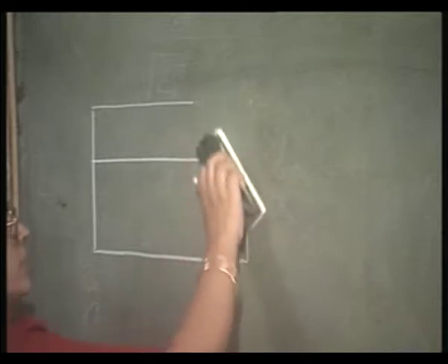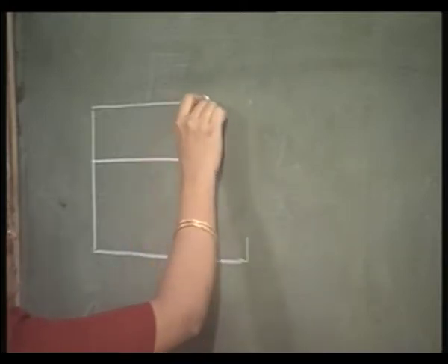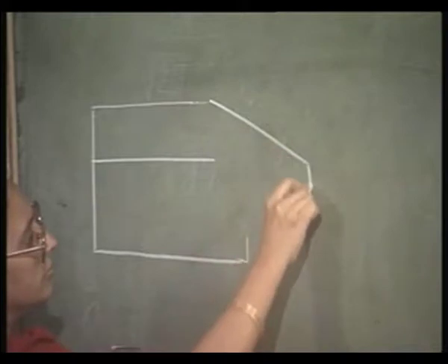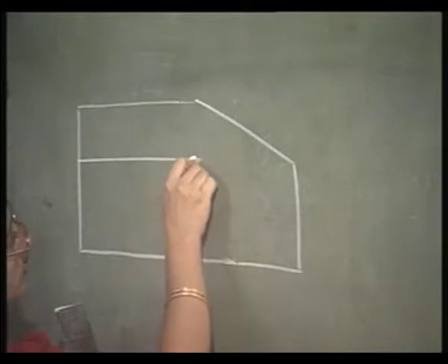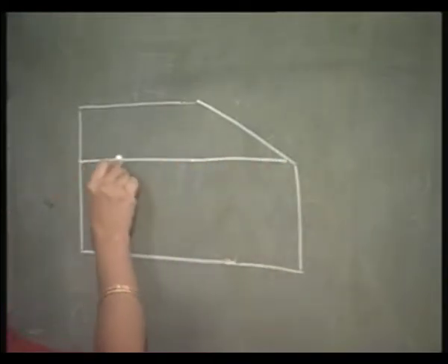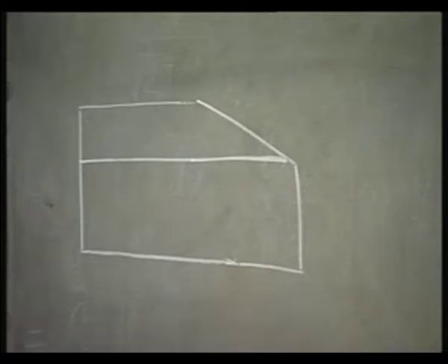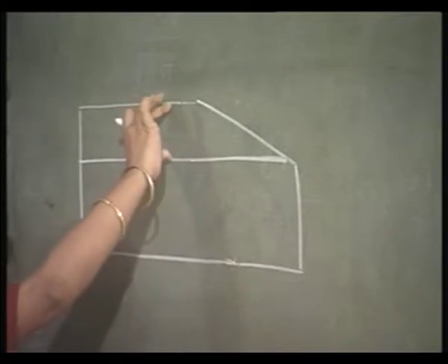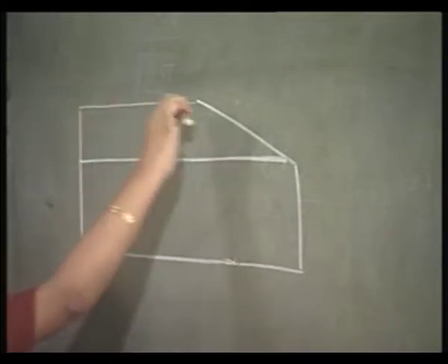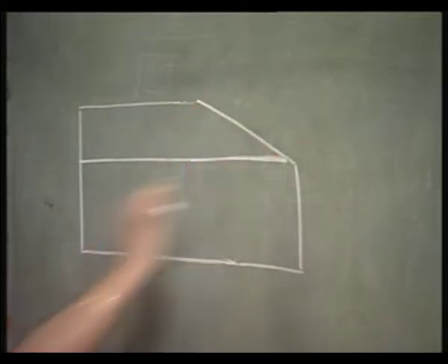Actually, this is done at a very small angle so that it looks somewhat like this. Why is it done? This angle lapping is done to magnify the junction. If you do not do any angle lapping, the junction depth you are seeing is this. But if you angle lap it, you are extending this portion.